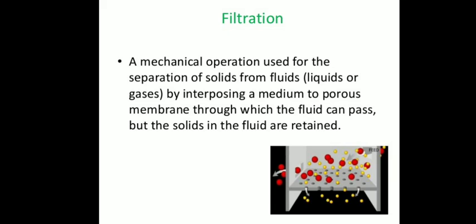Next step is your filtration. Now the filtration is a mechanical operation used for the separation of solid from the fluids. Here your fluid is your broth and solid matters are your cells, microbial concentration or the cell debris, and it may also contain your product. So simply by carrying out the filtration process we can separate these solid particles from the fluid by interposing a medium or porous membrane through which fluid can pass but the solids in the fluid are retained.